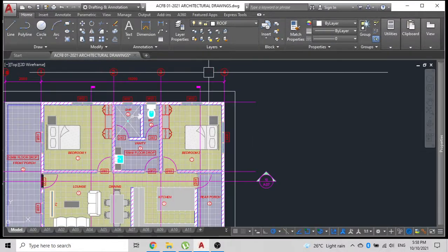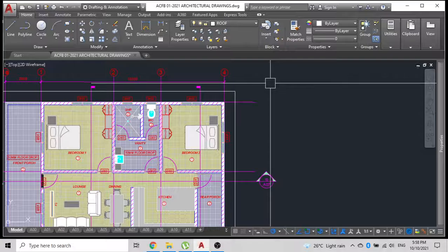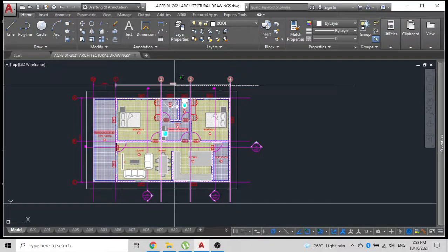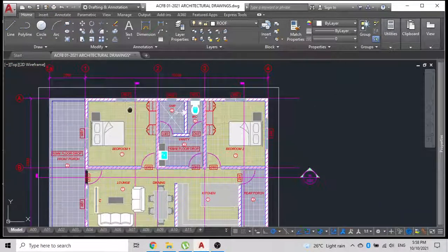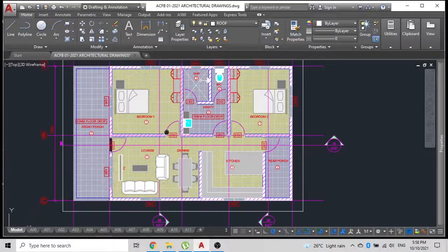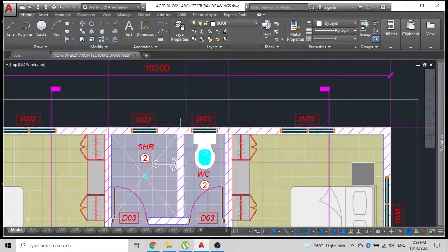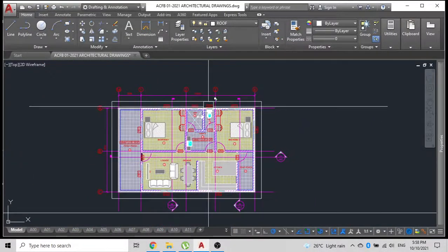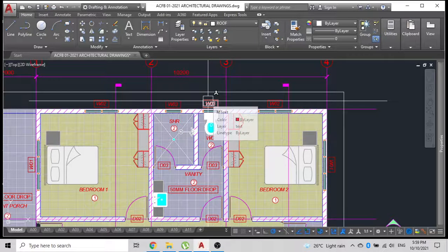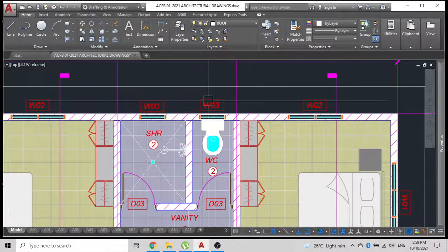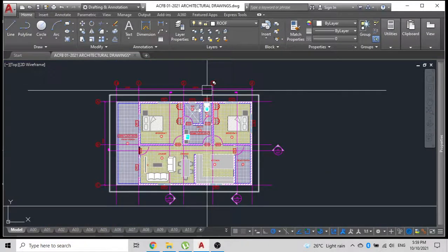And then, in order for me to successfully plot a good roof plan, I'll need to draw out everything that's important here. Wherever there is a restroom, there will be a terminal vent, but now I will not be using a terminal vent which penetrates through the roof. I'll be using a terminal vent which can be used above ground level.